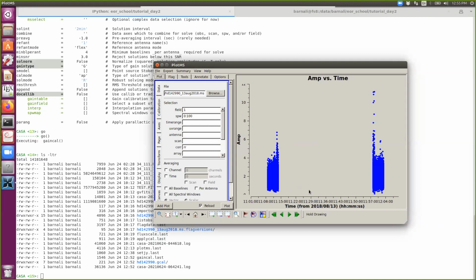And now I am solving for the phases, but I only have information after this 15 minutes of interval. So, assuming that phase information which I have after the 15 minutes, I am using it to calculate the phases for individual antennas for these 2 minutes of interval. If I am clear, I'm not sure if I'm clear or not. But you see that what I calibrated, phase calibrate, is after the 15 minutes, but I am solving within this.